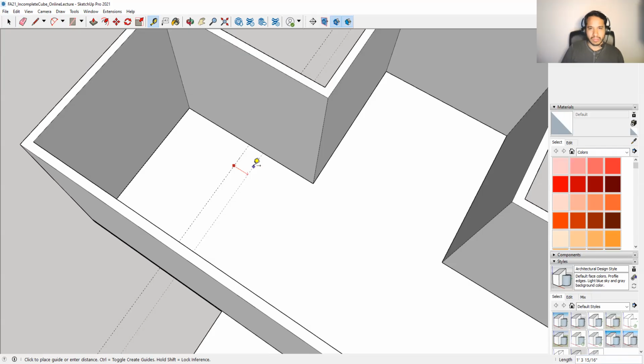Typically, interior walls are closer to about 4 inches, but they vary in width, and if we're talking about insulation and things like that, they could get pretty thick pretty quickly. So we're just going to keep everything the same. Since our exterior walls are 6 inches, the interior walls will also be 6 inches. So I'll hit enter.